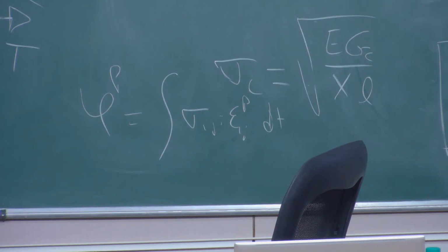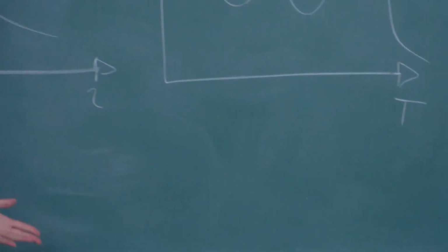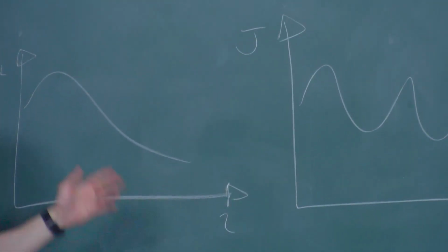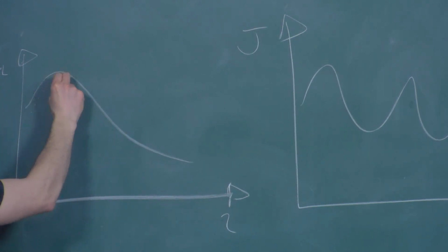So in conventional plasticity, in a large scale elastoplasticity, your stress concentration looks like this, and therefore your hydrogen concentration also looks like that. And they concluded that the steady state lattice hydrogen concentration, of course, is not dependent on how many traps you have. So adding carbides will not really benefit. And the only thing that will change is how long it took you to get to that point.